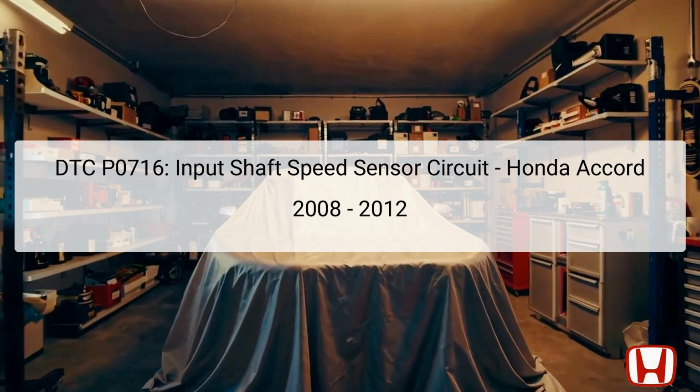DTC P0716, however, is primarily indicative of an electrical circuit problem and not due to mechanical failures within the transmission system. Key steps will involve utilizing the Honda Diagnostic System, HDS, checking the connections, and ensuring that the vehicle's onboard diagnostics are fully reviewed before any physical inspections.